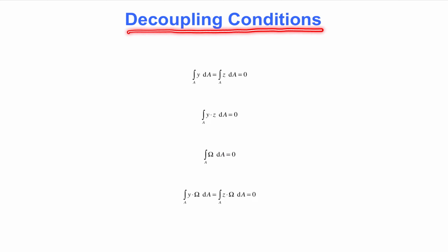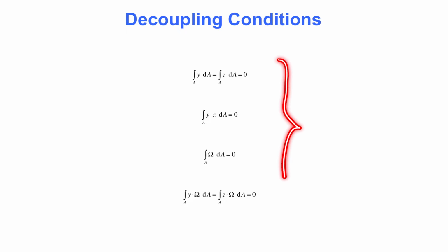In other words, we wish to review the conditions that must be met for the 6 off-diagonal elements of the matrix on the previous slide to vanish. These 6 conditions form an important part of any cross-section analysis. The first 2 conditions determine the y and z coordinate of the centroid of the cross-section. We must let the y and z axes originate at that point.